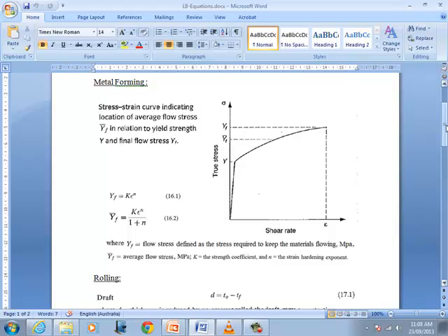For those materials which the change of the hardness is really big, we've got a higher value of N. For those materials which become slightly stronger, it's smaller. So, indeed, N is taking care of the slope of the curve within this region. It's a curve, it's not a straight line, but if we do draw tangent straight lines to the curve, the slope of the straight lines can be represented by this parameter. Okay?